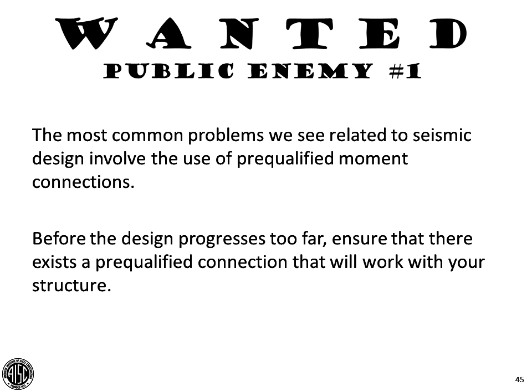So that can be accomplished either by having a pre-qualified connection out of AISC 358, or you would have to physically run your own testing program essentially on these details to make sure you satisfy the requirements that are laid out in, I believe it's Chapter K of the provisions.